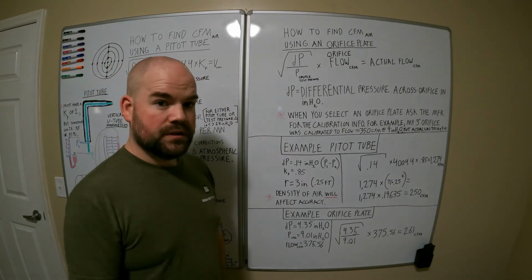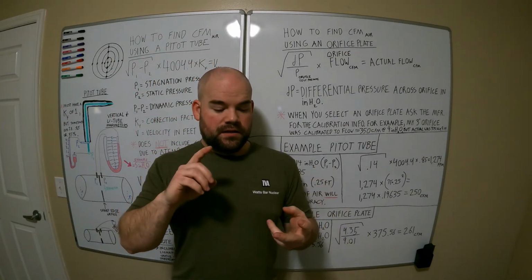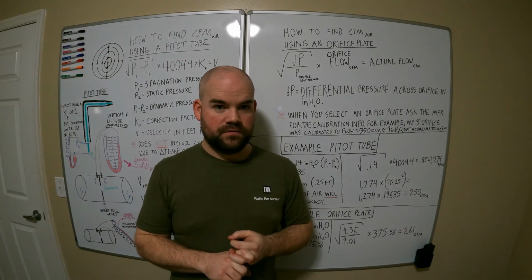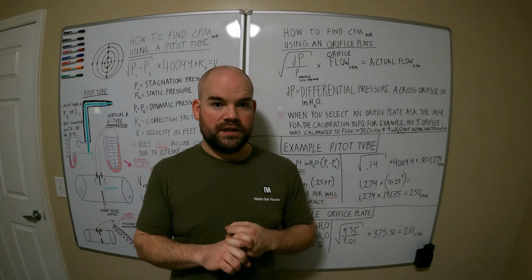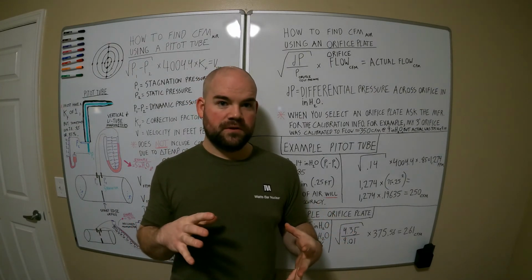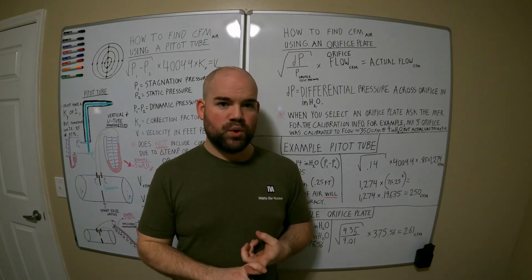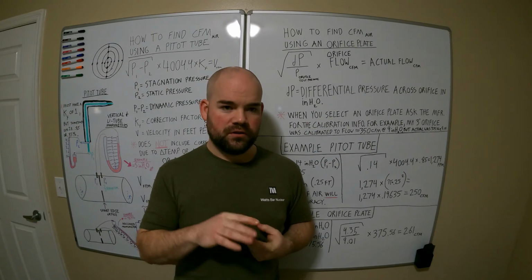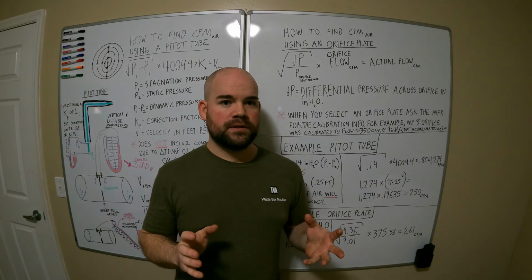But anyway, just to recap that last little bit on a port, the CFM is not going to change if you increase atmosphere. You're only increasing the amount of oxygen in the same space, occupying that same cubic foot, okay? So develop your ports, keep flow testing, do porting, flow test some more, and get that port as optimal as possible at all the lift ranges. Keep your velocities high. All that is super important, okay?